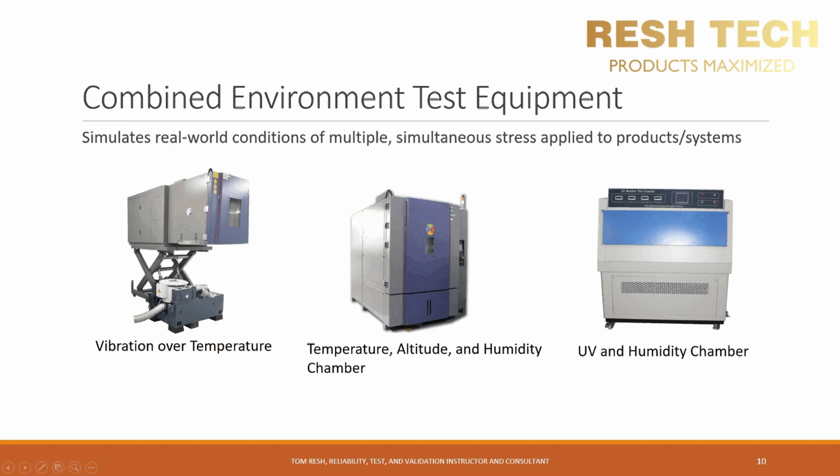Last but not least, let's talk about combined environment test equipment. There are other variations, but three major types of test equipment I would like to highlight for this video are: The vibration over temperature chamber, which exposes a product or system to simultaneous temperature and mechanical stresses. A couple of examples of this in the real world are automotive and aerospace vehicles and systems, which are exposed to both temperature and mechanical loads simultaneously.